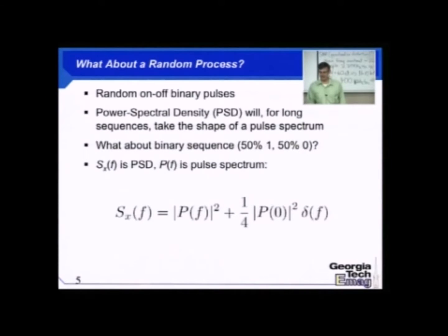Or if I want to work in the time domain, I'm a real masochist. I convolve signals. I convolve X with my channel impulse response. That gives me my output. That works great for deterministic signals. But let's say I'm transmitting a packet with 1,000 bits in it. Those 1,000 bits could be whatever that we want them to be, right? You have to be prepared to transmit every possible combination. Well, in order to figure out how my system operates, will I have to simulate and analyze every potential combination of bits for that packet?